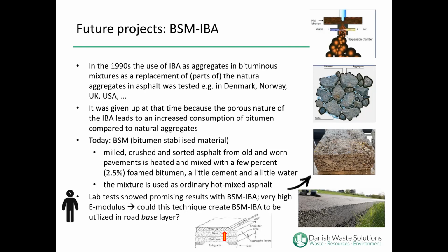People ask whether this can be used for bottom ash, and some lab tests have been done in order to test this hypothesis. The test results were promising in the sense that a very high E-modulus of the bitumen stabilized bottom ash was measured.